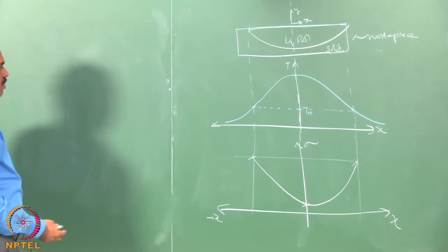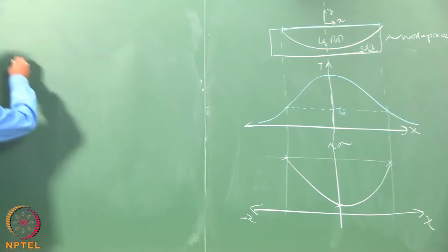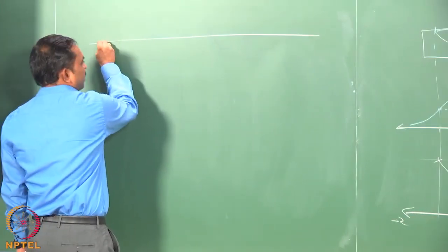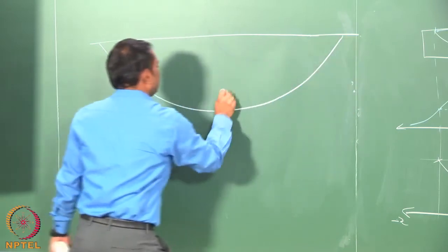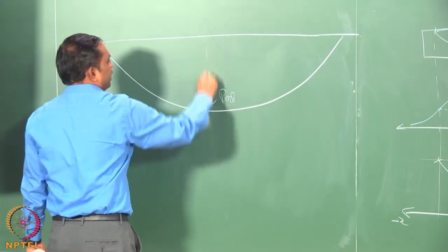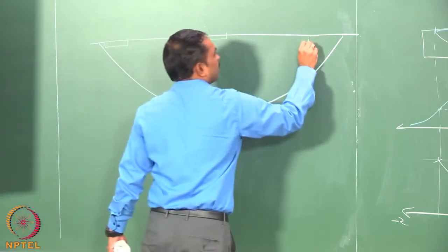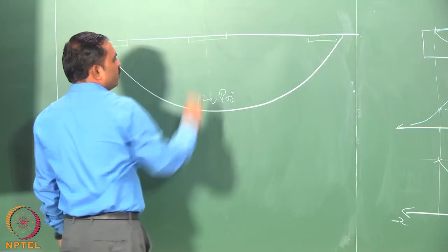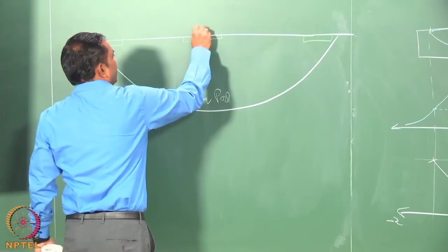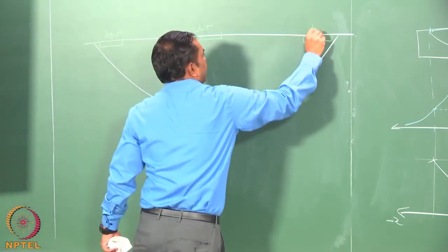So, which means that on the liquid melt pool, how does this kind of surface tension difference play a role in the flow is something that we can illustrate, and for that I would just draw the pool much bigger and then show you. Consider the elements like this, at the center, an element here and an element here. Here you see that because the temperature is high, the surface tension is low. So, here it is low sigma, this is high sigma, then here also is high sigma.